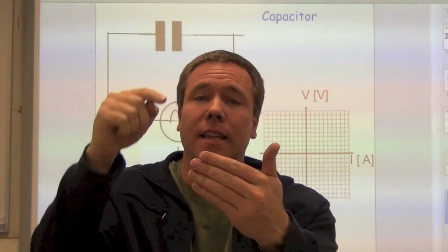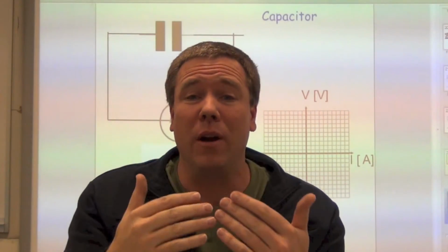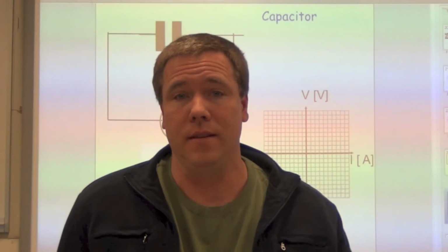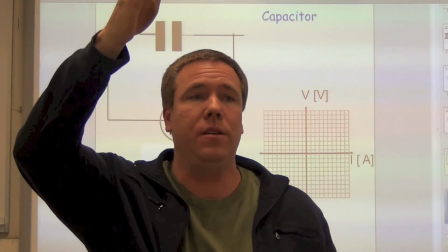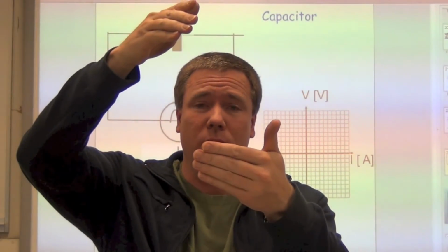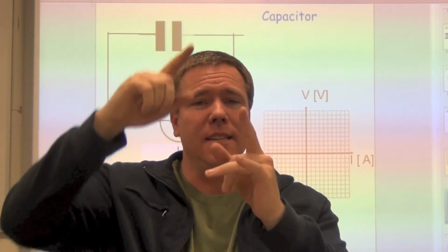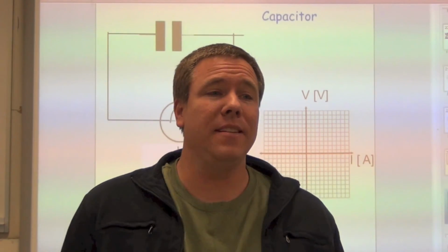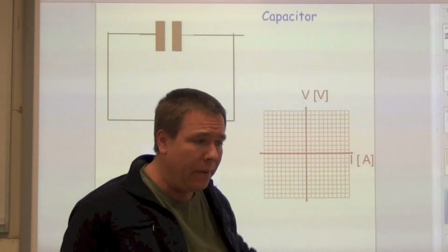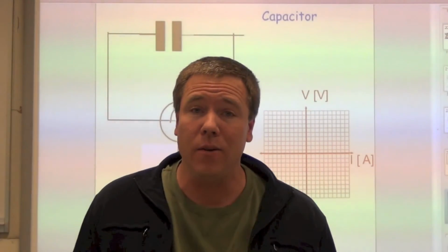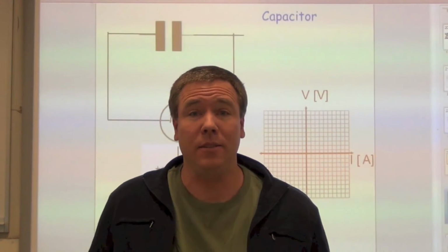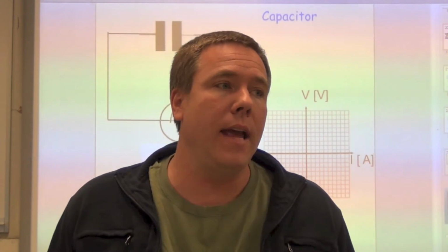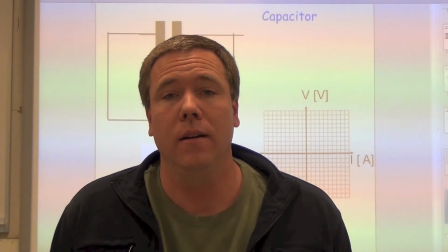And if in the current, in the denominator, we have 0, then what do we have for resistance? Or can we even speak to the resistance? What happens when you take a number, say voltage, and divide by 0, because there is no current? It's not infinite, is it? It's rather undefined. So we'd have to say that the capacitor, unlike all these other components, does not obey Ohm's law. The capacitor disobeys Ohm's law, or actually we should just say it ignores it completely. If you don't have any current through, then you can't even talk about Ohm's law.